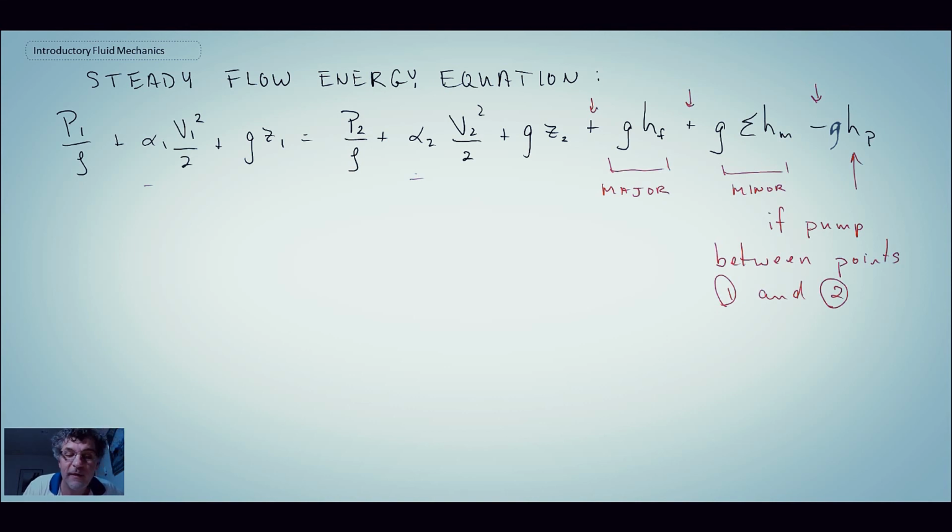So that is the steady flow energy equation, fairly straightforward in terms of just looking what components you might have within a piping system, adding up the minor losses, computing the friction factor for whatever flow regime you might be, laminar or turbulent, and you add them all up, and you can then do pressure drop calculations and different things like that with the steady flow energy equation. So that concludes our segment looking at minor losses in piping systems.